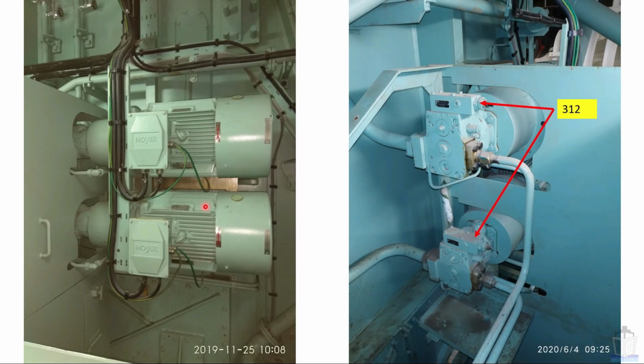These are two electrical driven pumps, basically motors, and these two are pumps. These two are relief valves, valve number 312. This is called the minimess coupling, which is a pressure checkpoint for these individual pumps. In case this pump is malfunctioning or generating less pressure, you can just connect a pressure gauge over here and check whether there is a problem inside the pump or not. If it is not building up sufficient pressure, that means either this relief valve has a problem or the pump is faulty. So accordingly you can take action.